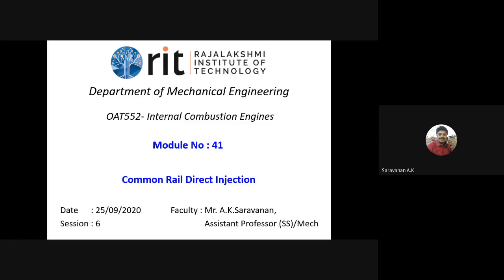Traditional diesel engines must produce fuel pressure for every injection, but in CRDI engines, the pressure is generated independently of the injection sequence and remains constant in the fuel line, right? Unlike single pumping systems, the pressure buildup and spraying are separated in the common rail direct injection system.